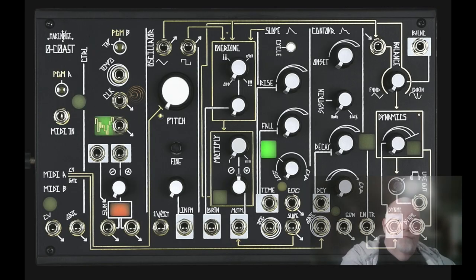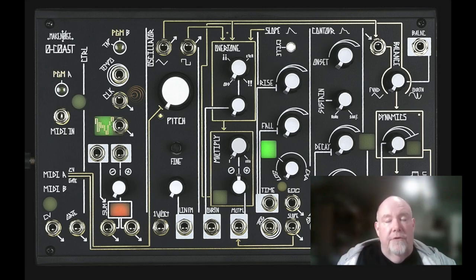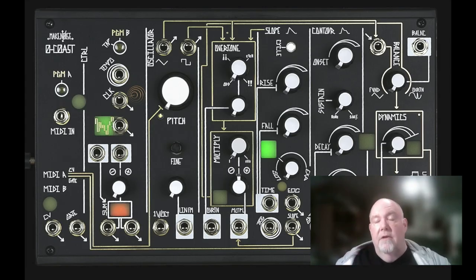There we go. It's similar to West Coast synthesizers such as those from Buchla and Serge. However, it shares some things in common with East Coast synthesizers from Moog and ARP as examples. Specifically, it has the ability to track pitch at a 1 volt per octave scale, and it has the ability to be controlled by a keyboard via MIDI.